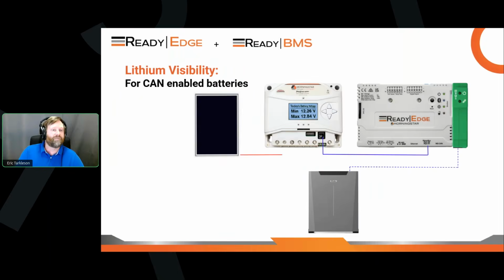And then finally, let's talk about the BMS block. The ReadyBMS is a CAN bus that is designed to interface with lithium batteries with a CAN bus. Right now, the ReadyEdge allows you to get all of the data available through the CAN bus onto the ReadyEdge, and then available via Modbus and some of the basic parameters in the ReadyEdge itself. So mostly this is going to be SOC, right? What is the state of charge that your battery says that it is?